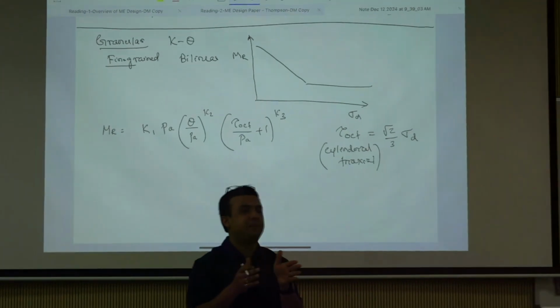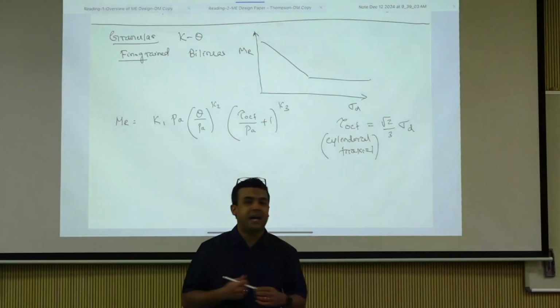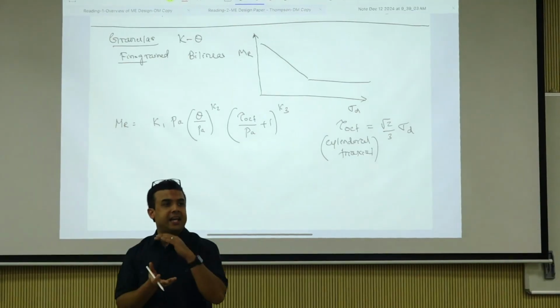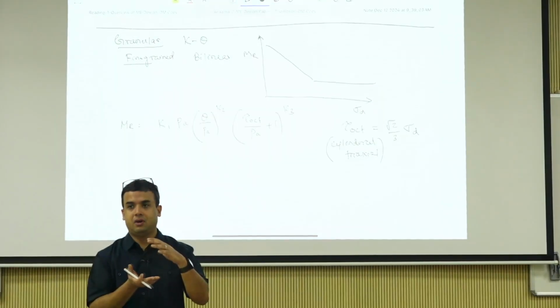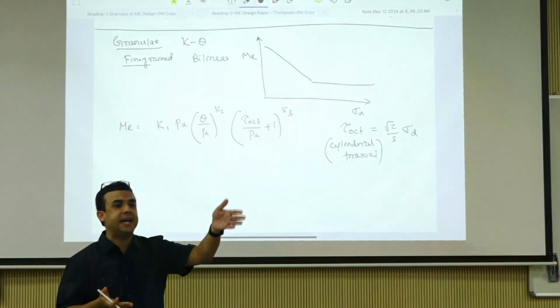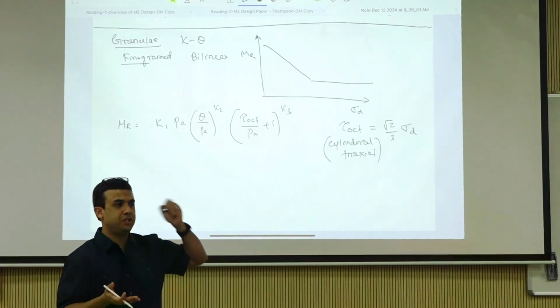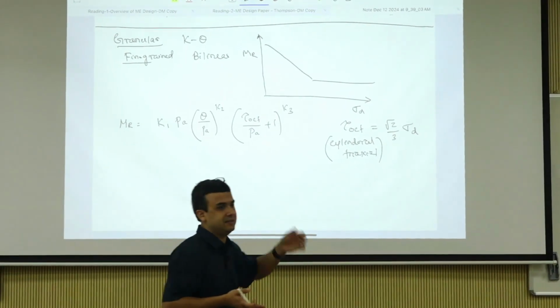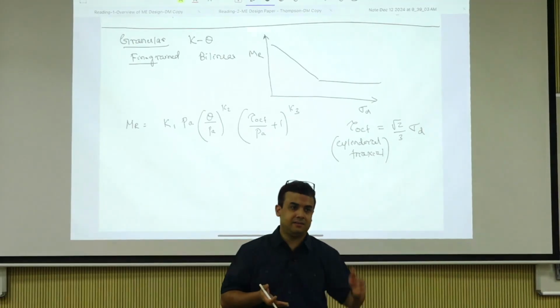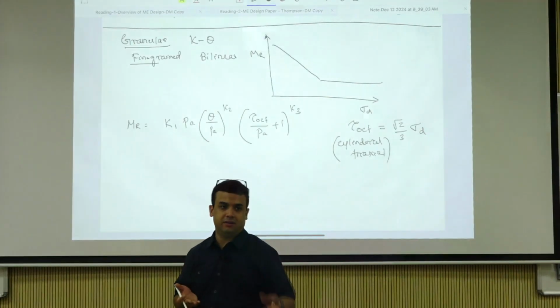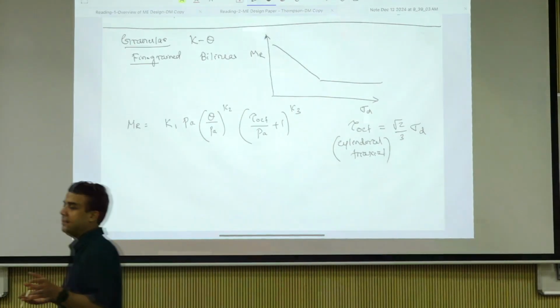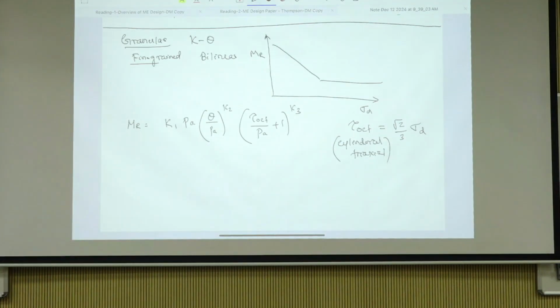The analysis part is done by what is known as a multi-layer elastic formulation or layered elastic theory, which is what your IIT PAVE is, which is what MnLayer is, Wesley is, there's many, Chevron is, all of them. It's the same thing, similar concepts.